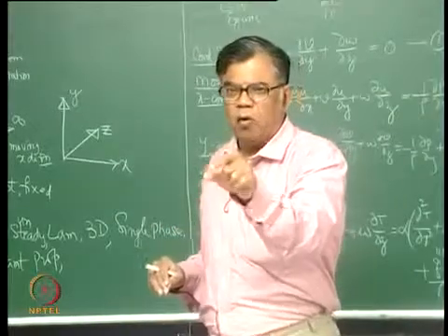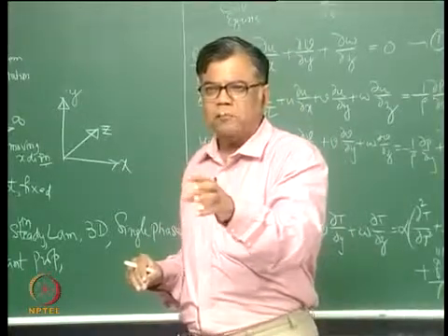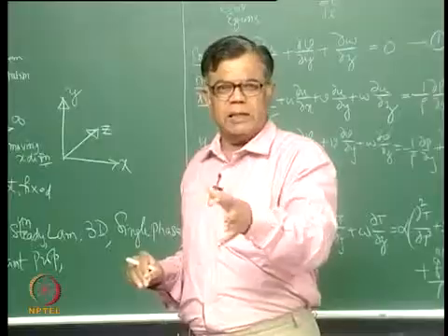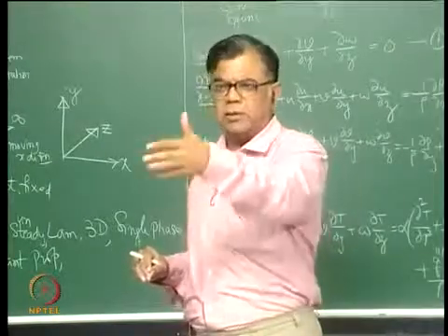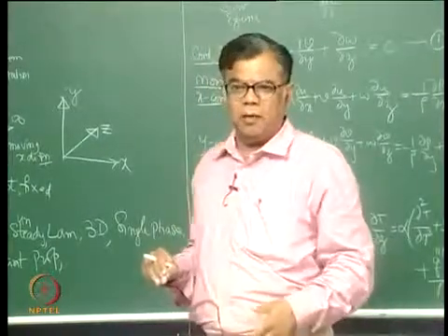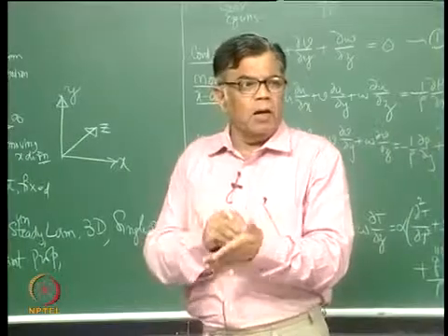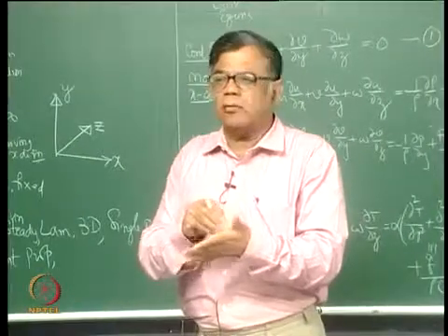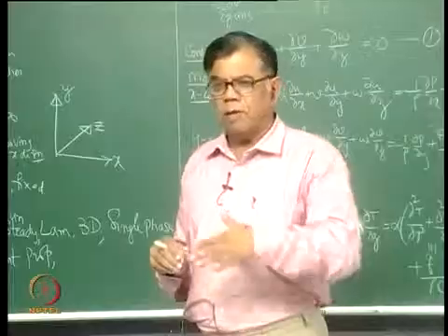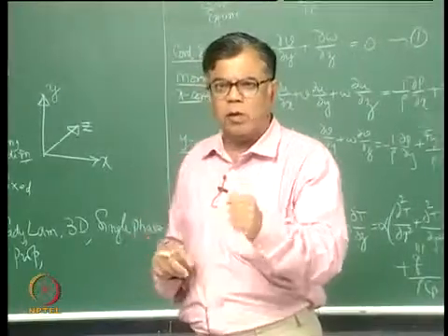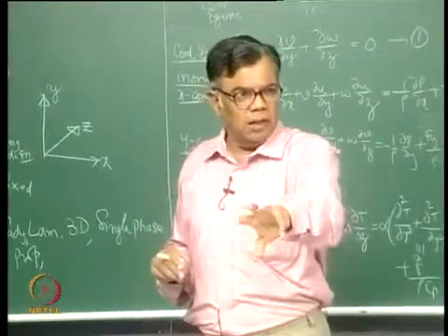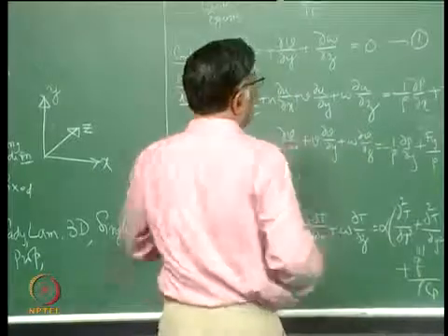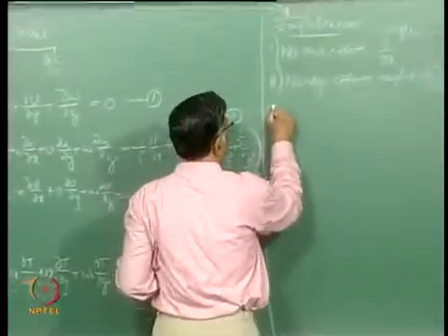In fact, that flow at x equal to 0, that is a leading edge thing that creates a lot of problems actually, especially in your numerical solution. If you are going to solve numerically, what condition are you going to put at x equal to 0 is a big problem. y equal to 0 is no problem, x equal to 0 what? That is a singularity situation there. Okay. No end effect, no edge effect.